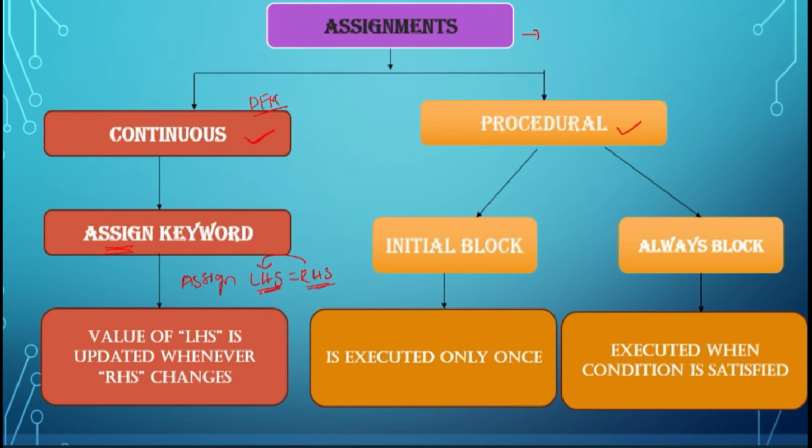Why? Because this LHS will be activated in the active region of Verilog. Since LHS is activated in the active region, any update in RHS will immediately get impacted on the LHS. Okay, so this is basically what the assign keyword is.